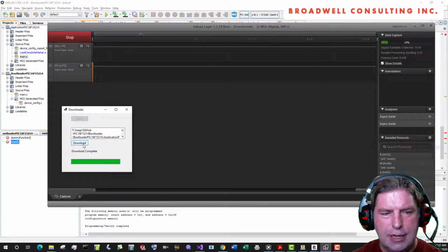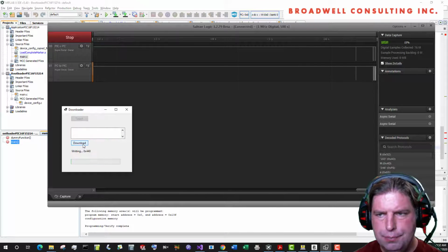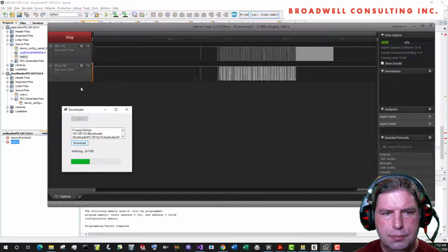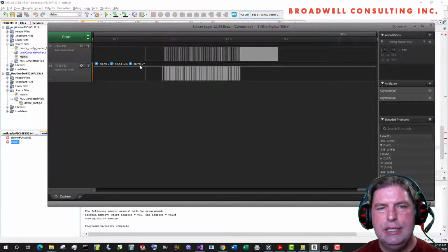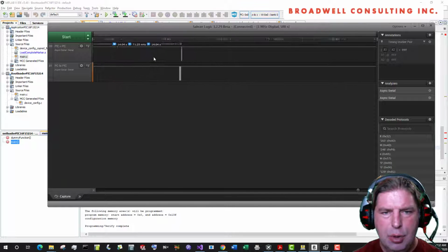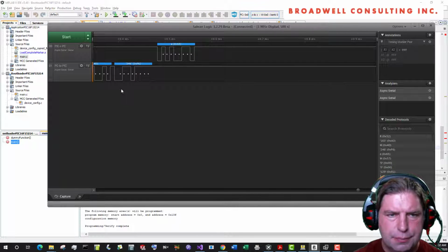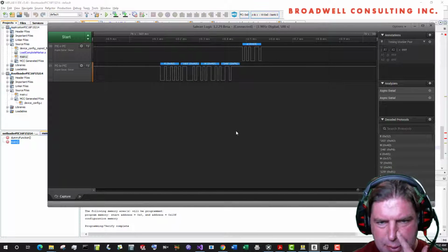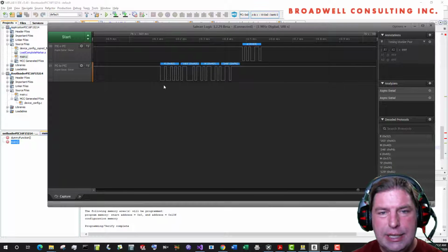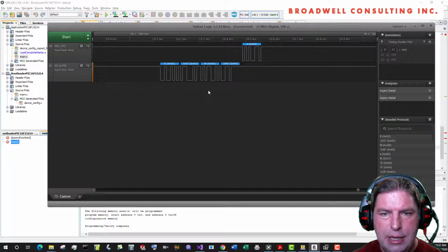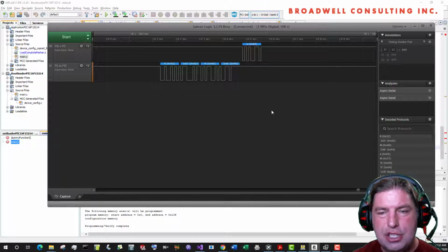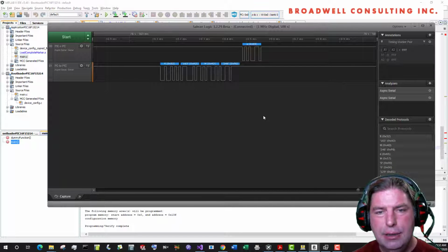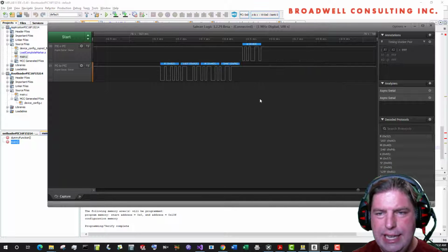Now let's take a look on a logic analyzer as we do the same download. And we can see in here the same set of steps. What we have coming in, at some point in the past, the bootloader announced itself with its startup sequence. And we can see that we send a 52, A3, 4D, F6. That's just our magic, let's start bootloading 32-bit key, at which point the bootloader responds with a lowercase e, indicating that it is erasing.